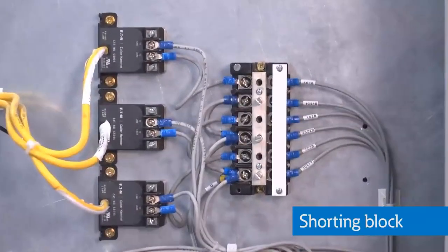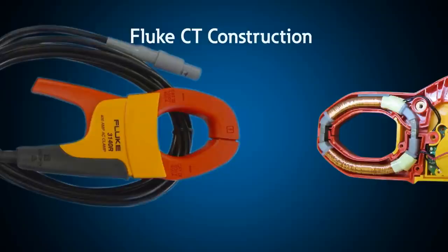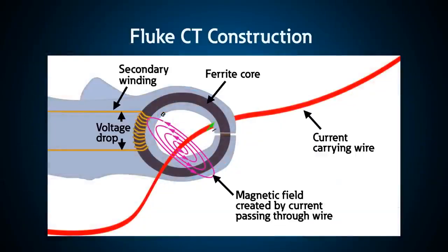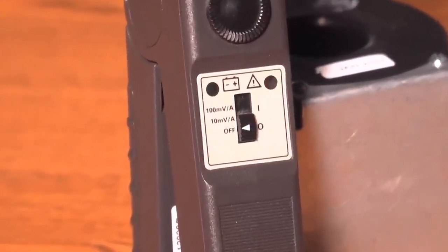or a temporary jumper. All CTs output a current that is then used for metering, but temporary CTs, like those used in Fluke and other power quality instruments, add a terminating resistor on the secondary winding so that they output a voltage and can be open circuited when connecting the meter.